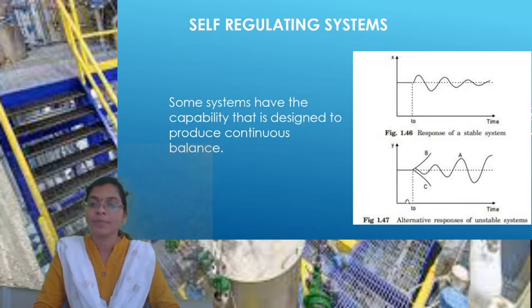So this is called a stable system or self-regulatory system. Now observe here: I have taken an unstable system. Our desired value is the unit step, which I indicated with a dotted line. First you tell me, A: is the output of A a stable or self-regulatory system? No. Why? Because initially the deviations are small and the controller measures them, but is there any reduction of the deviation?